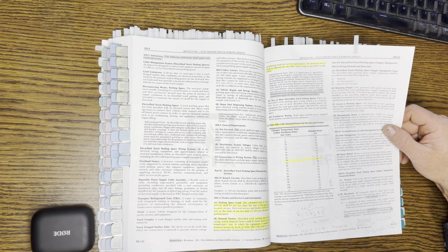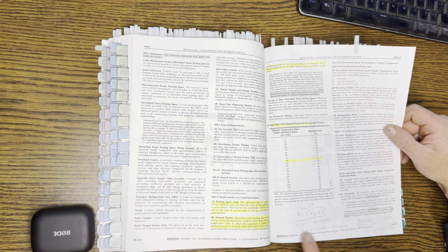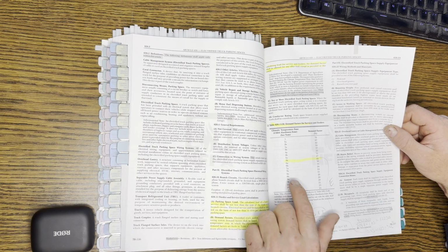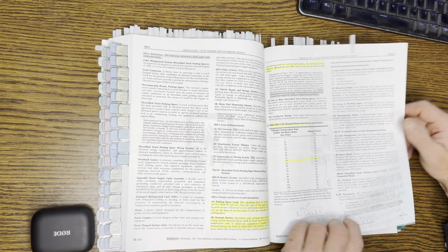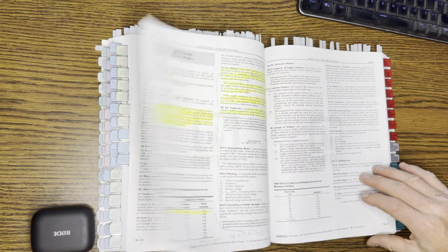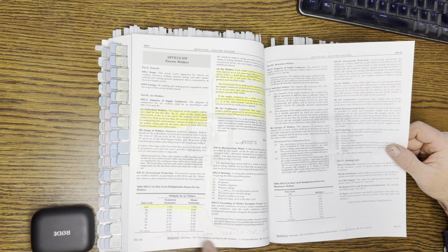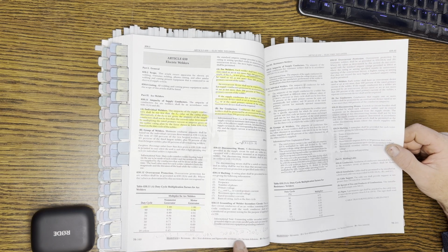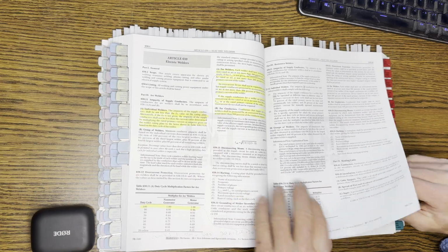Square root of 3, I think it's 1.73, just keep that in mind for power. And I give you an example case here and some that I quoted from the actual test that I created, but it actually came from the test. So just to help you out, here's another example, welding 30 amps, how to calculate your actual required load, which is 200% in this case. It goes through electric welders.